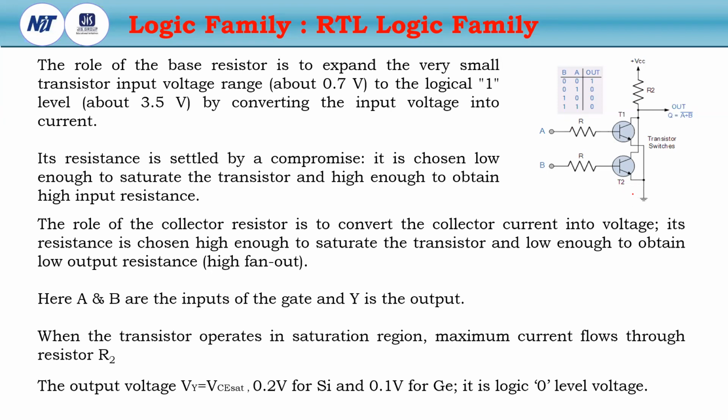So the consideration is that we should choose a low enough base resistance to saturate the transistors and a high enough base resistor to obtain the high input resistance.